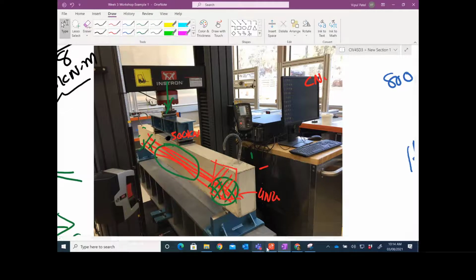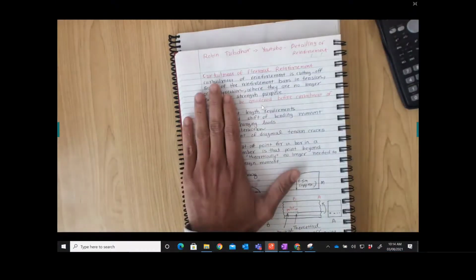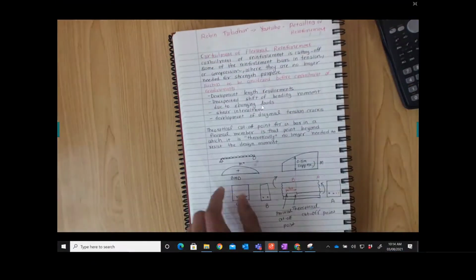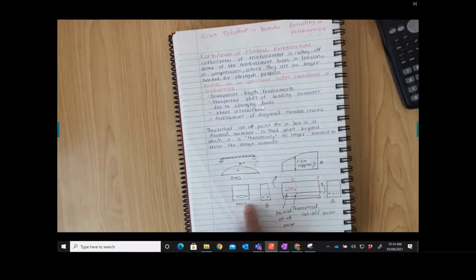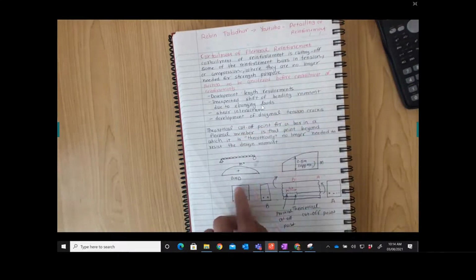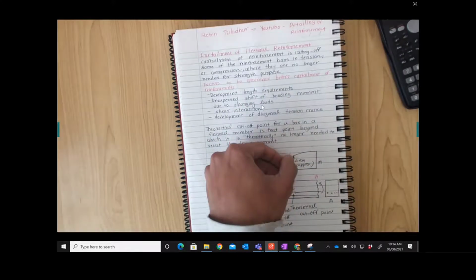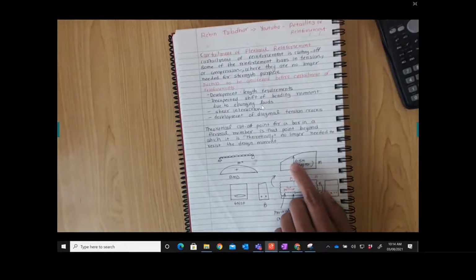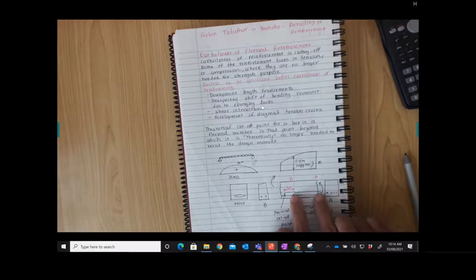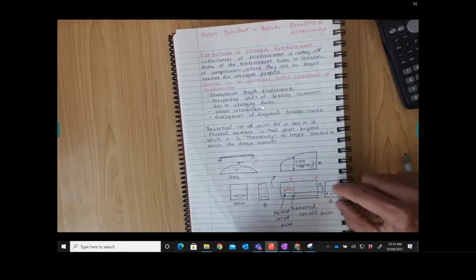Curtailment. The standard has a clause; probably later on I will show you that one. So this curtailment is saying that if you have, let's say, this is the bending moment and you have 4 and 20 bars, basically these are the moments here, right? You have this maximum moment M star. Then if you come halfway through, like a halfway moment, what you need to know is that this is the actual reinforcement going here. So in that case you have 4 bars.